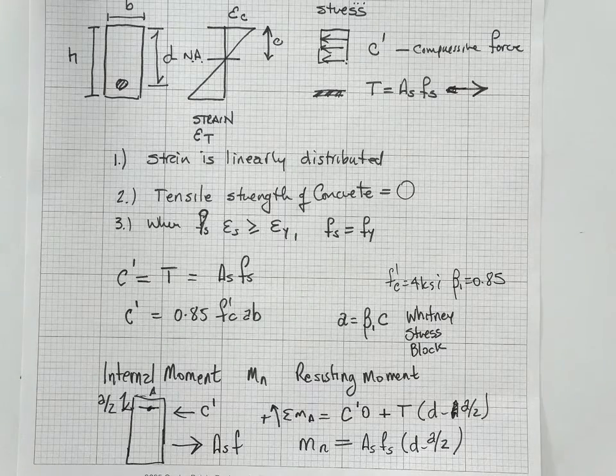If we were to take the beam and cut it in the middle, in order for there to be a balanced moment, there has to be an externally applied moment. That's what's causing it to sag. The beam has to have an internal moment that's the same size to resist it. And if it can't handle that moment without failing, then that's our ultimate limit state.